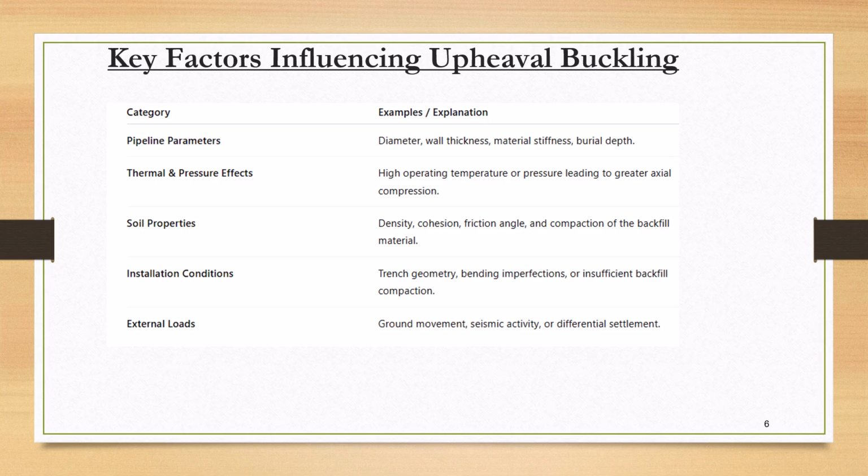So roughly 800 mm of soil cover will actually be giving resistance to the displacement caused by the axial compressive force. This way, when we learn the actual steps and formulas, we will see the impact of imperfections that arise from the soil terrain and the actual nature of onshore pipeline systems.